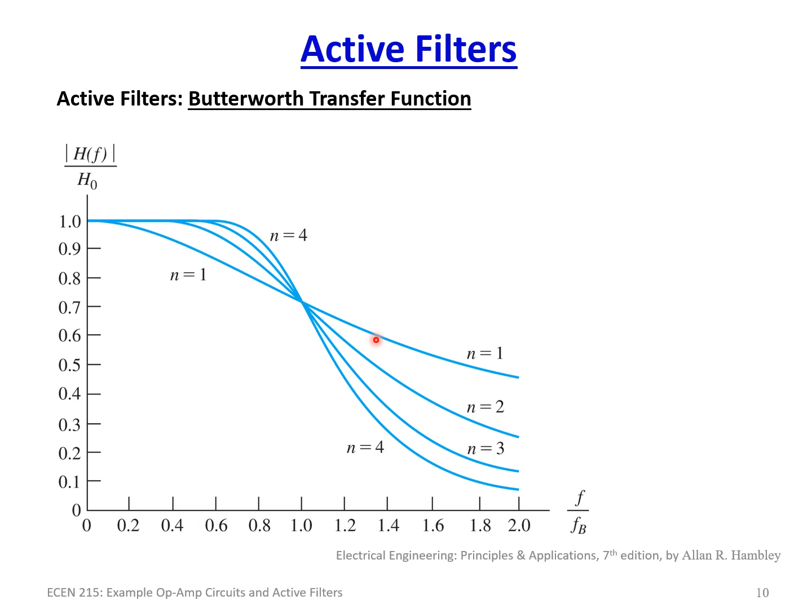But sometimes, especially if you're doing band reject and band pass filters, you want to create a roll-off that is really steep, so that you get to the frequency of interest and it turns on. If you're doing a band pass, it turns on and then it turns off. You've got a real narrow band and it's really sharp. That would be the goal. In that case, you're going to want a higher order, but that complicates things.